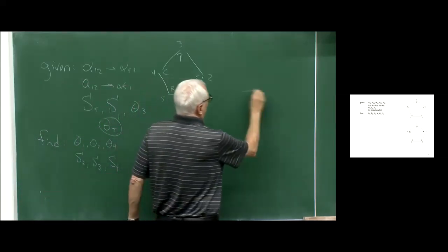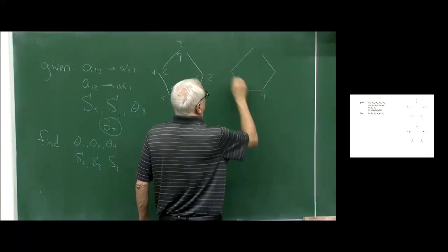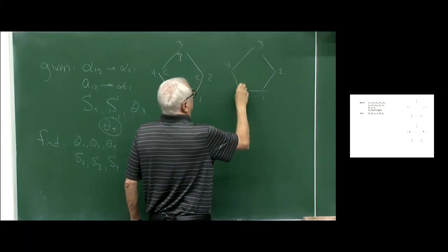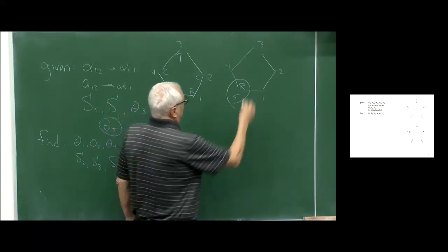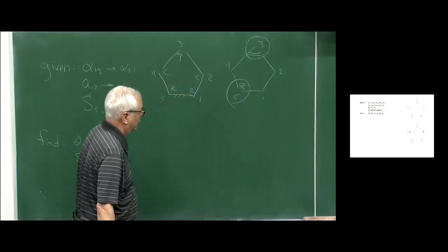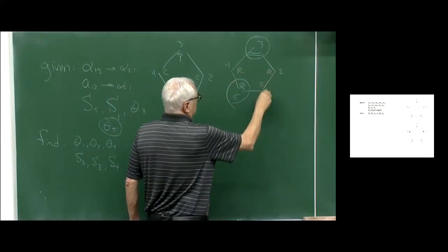Let's draw the planar representation of the spherical mechanism. And I'm going to circle theta 5 because that's given. I'm going to circle theta 3 because that's where the prismatic was. And then these other ones over here all map as revolutes.